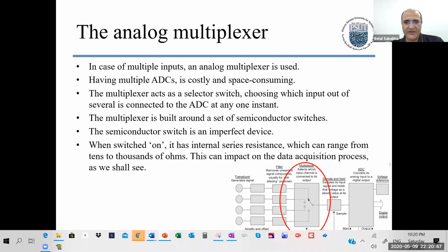Okay, and this multiplexer now. This multiplexer is something we program, and we tell it to select and connect to our sample and hold and ADC circuit. Connect the A to D to port A0 or 1 or 2, okay, multiplexer. And this has control inside any of the registers we're going to deal with. Now this is the sample and hold circuit.